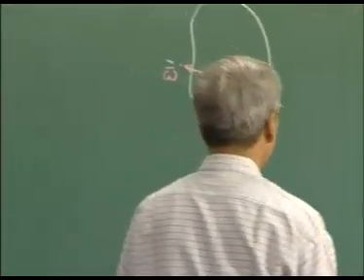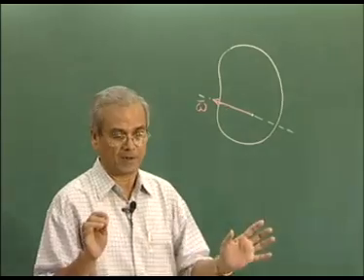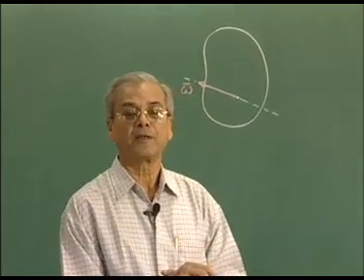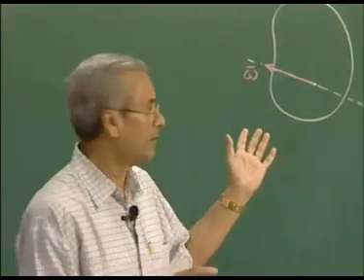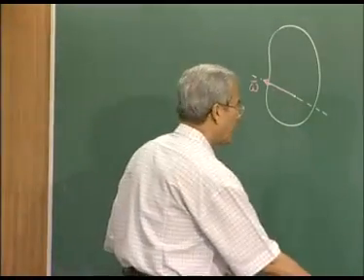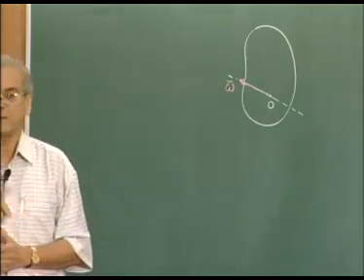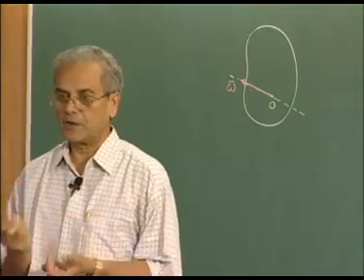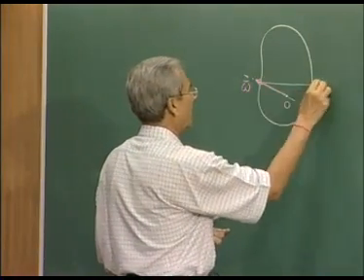It should also be remembered that this angular velocity vector is neither fixed in space nor fixed with respect to the material body. It executes a motion with this point O fixed in space, generating a cone which we call the space cone.